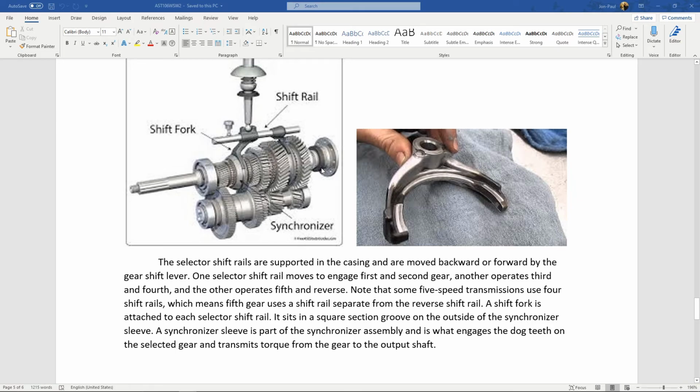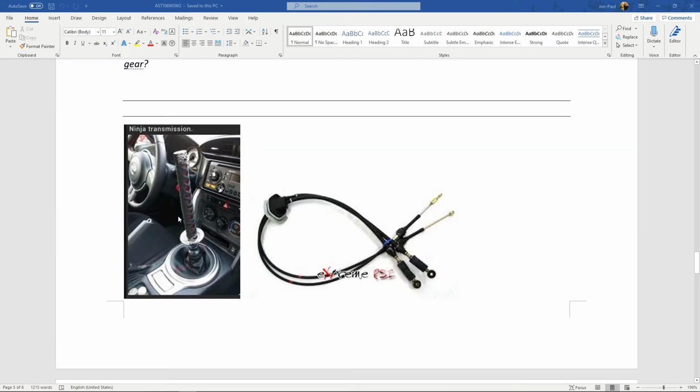So you thought you were shifting into first, and because the forward and back is a separate cable, there'll always be 2, right? One cable is for left and right, one cable is for forward and back. So you would go left and forward. The left and right cable was broken, but the forward and backward one was working correctly. So you thought you were going into first, but really you were shifting into third. And it would stall the vehicle, and it would sputter and slip the clutch and everything. And those were both on Ford Escorts, maybe Escapes, either way, where they were coming apart.